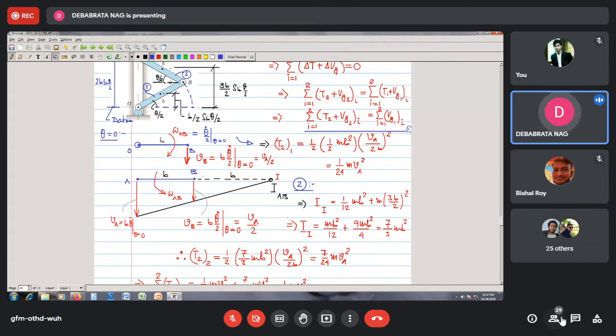So now since this member is turning about point I, I can directly calculate the kinetic energy just like the way I have calculated it here. First you see the omega AB, that means this member's angular velocity is going to be Va divided by 2B, right?